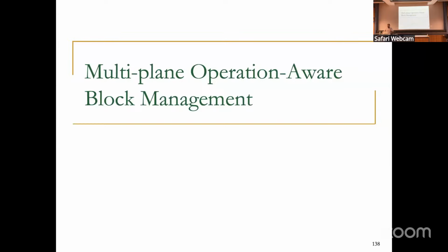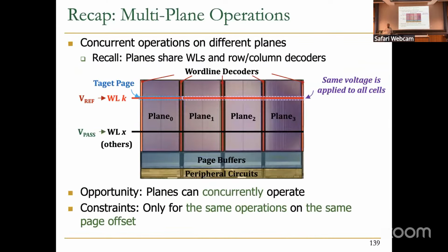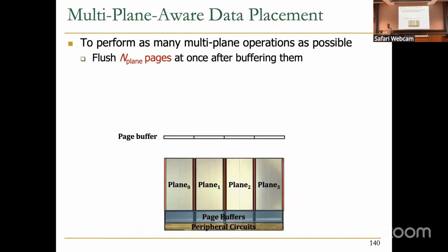Okay. Then I will continue with multiplane operation aware block management. Recall about multiplane operation, and also recall what your colleagues asked about, that garbage collection can mess up the multiplane operations. So you can actually do the block management and garbage collection aware of multiplanes.